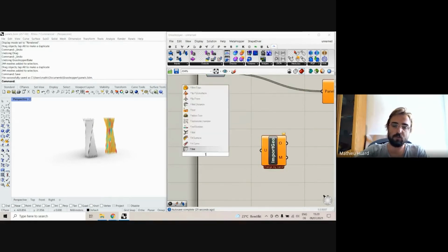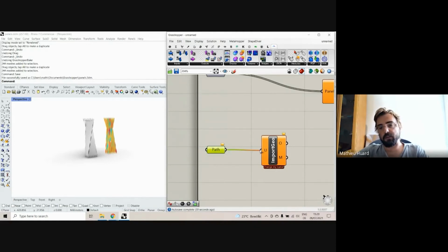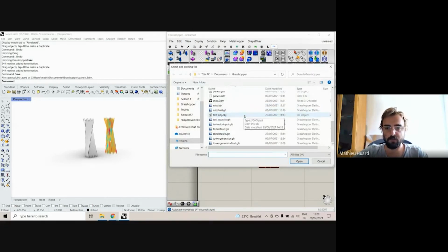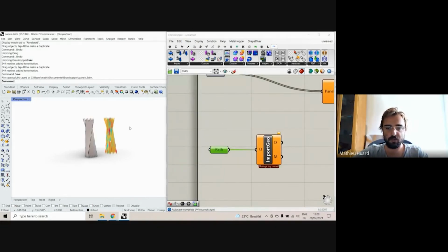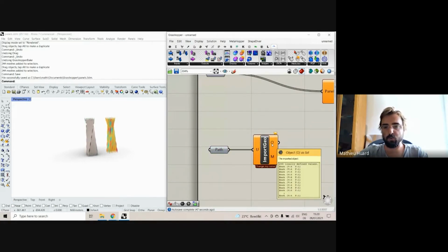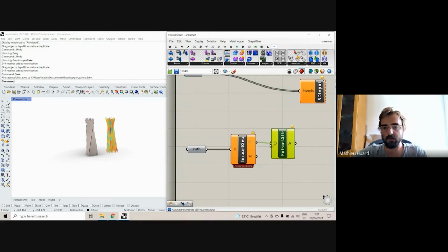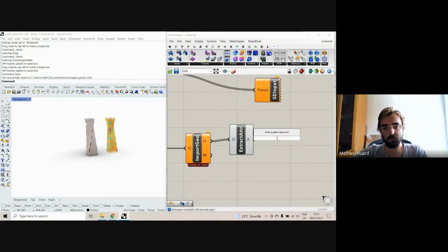So these imports, what's good also for debugging purposes, is that they're compatible both with an online URL or uploading a file directly online, but also with local paths, so you can test locally. So here, if I reference my panels.3dm file that I just created, I will import all these meshes. And importantly, I will import them with their attributes, right? Since I didn't really set any, if the material is not in there, I'm not sure what I'll get.